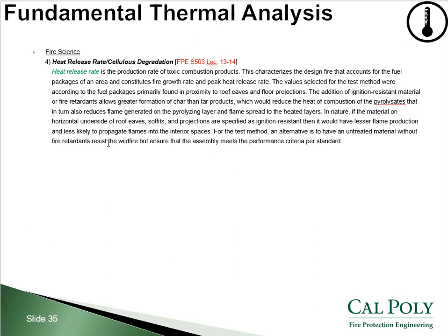Third, does applying fire retardants to the roof eaves and floor projections affect fire dynamics? Yes, of course. Heat release rate is the production rate of toxic combustion products. This characterizes the design fire that accounts for the fuel packages of an area and constitutes fire growth rate and peak heat release rate. The values selected for the test method were according to the fuel package primarily found in proximity to roof eaves and floor projections.